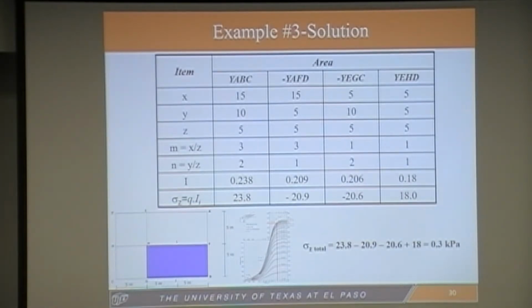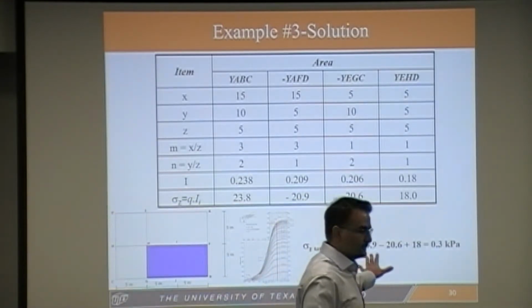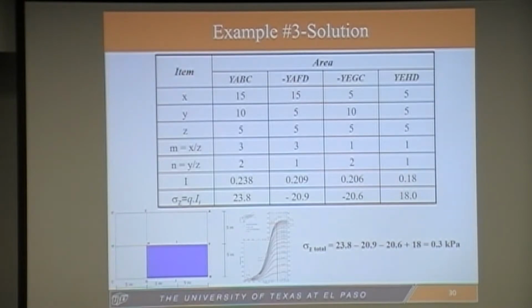Now let's quickly talk a little bit, maybe in 1 minute, about one of the implications of what we have here. Many of you have seen that in new designs, in luxury homes, they put a big, huge swimming pool right at the slope, right? Because they want to have the view, right? So right at the slope, you have the swimming pool. What's the implication of that? You have a swimming pool, a concentration of mass right at the slope, right? And a lot of times when they didn't reinforce the slope, it fails. This is the reason for that, right? Because the magnitude of the stresses is high right at the edge, and it will result in the failure. So that's one example that you might consider when you're looking at the usage of these applications.